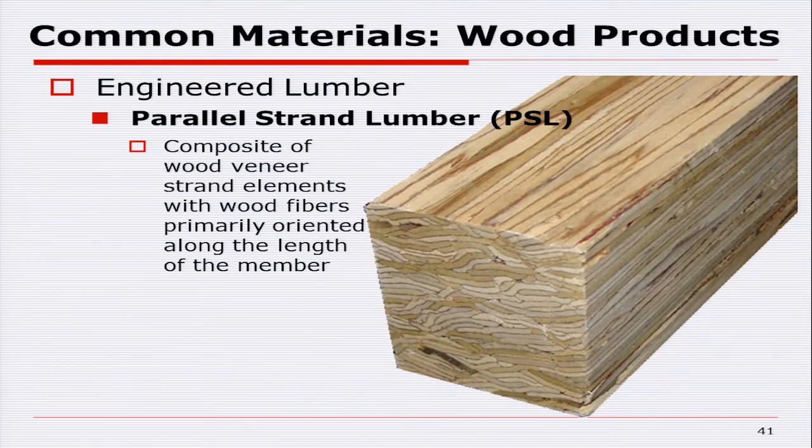The other thing that we do is, when you start peeling off wood veneers, you start running that thing into the log, and you're not getting out full sheets of veneer. It starts throwing off some chunks, and some of those pieces are pretty long. And then you get some veneers that are just really bad because they have huge knots in them and they don't want to use them for plywood. What they do is they take those veneers, those ones that aren't full, or have big knots, and they clip them. They make them into thin strips. Some of those strips are long, some are short, doesn't make any difference. They then glue them all together and they get what we call parallel strand lumber.